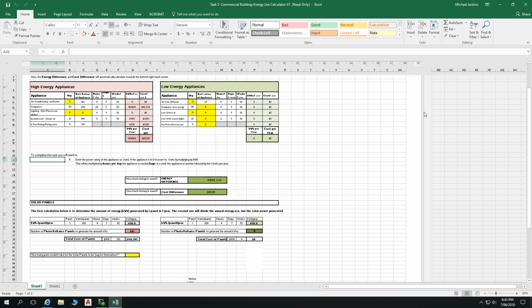So within here we're utilising 60 watt fluorescent globes. We have 125,000 lumens we have to achieve. We can look at the lumens produced from a 60 watt fluorescent globe, and then put that in there, so work out how many we need. So we divide our 125,000 by their lumen output, specify our number, and then specify what their wattage is.